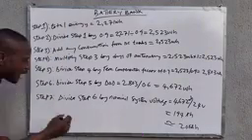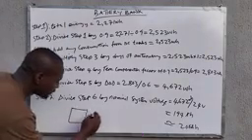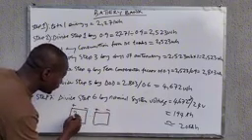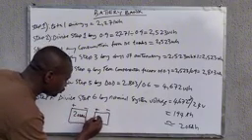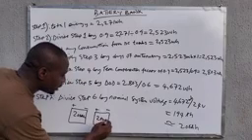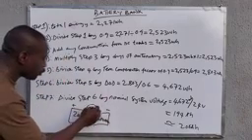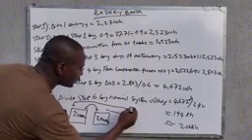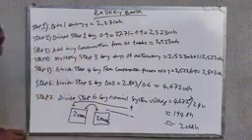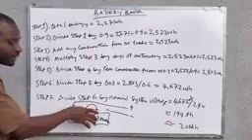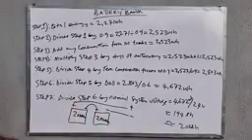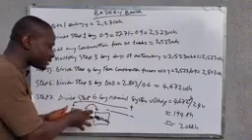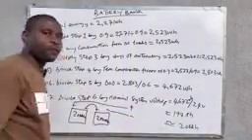And you can have something like this. This is two batteries, positive, negative, positive, negative. This is 200 Ah, 200 Ah. Since it is 24 volts, you connect them in series. So this will be your positive and your negative. This is what you will send to the inverter, and also connect your charge controller to this battery bank. So the two batteries are connected in series. Why? Because it is a 24 volt system.